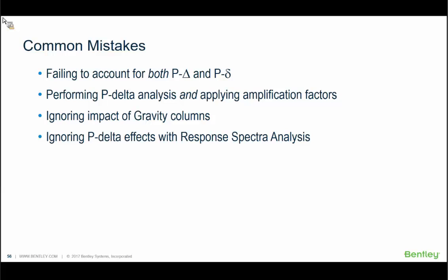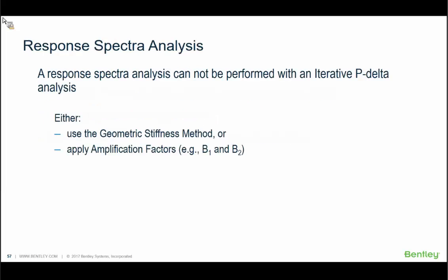This fourth one is somewhat controversial, but P-delta effects are often unintentionally ignored when a response spectra analysis is performed. The reason is that the response spectra analysis method is incompatible with an iterative P-delta analysis. You can't do both simultaneously.